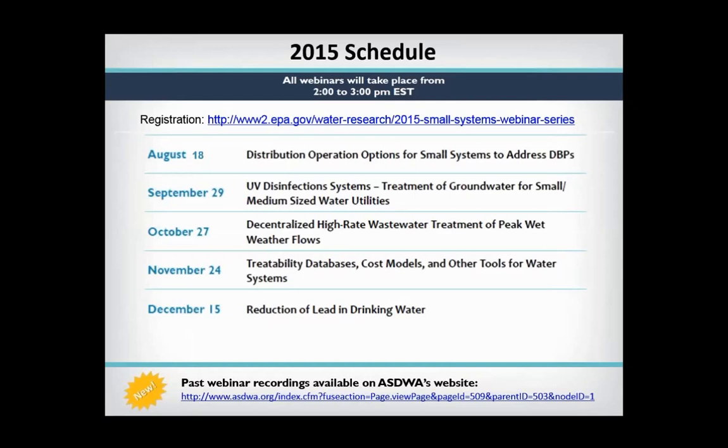The question I would ask is, are the low copper readings in relatively new sites, or are these all 20-plus-year-old sites? And I would think about what the background water chemistry is and whether it's likely that the new sites would even have a copper problem. Even though small amounts of orthophosphate can retard the aging, if it's not an aggressive water to even new copper, it doesn't matter. You'll get higher copper levels, but it's not anywhere near any kind of a health threshold of concern.